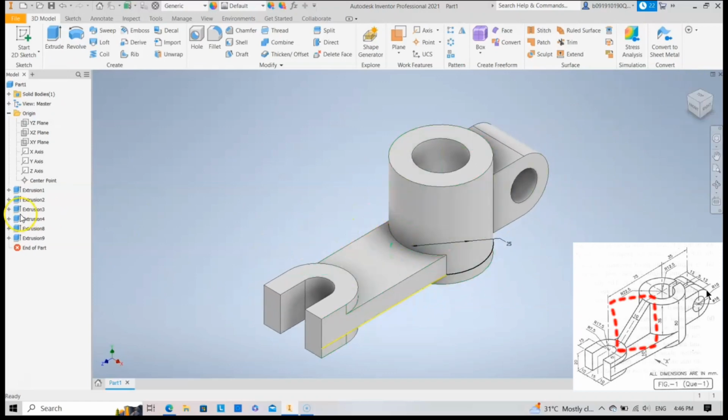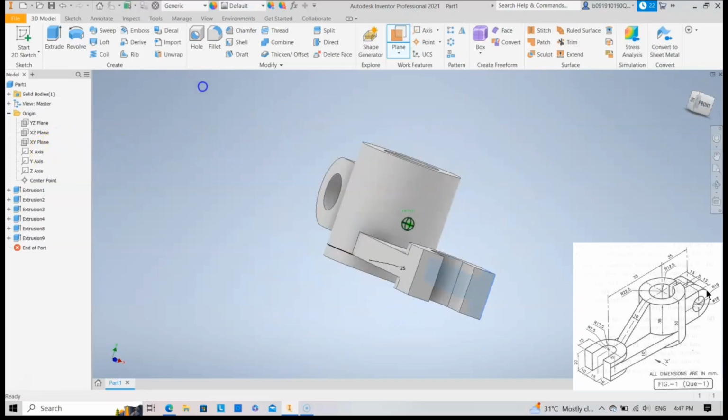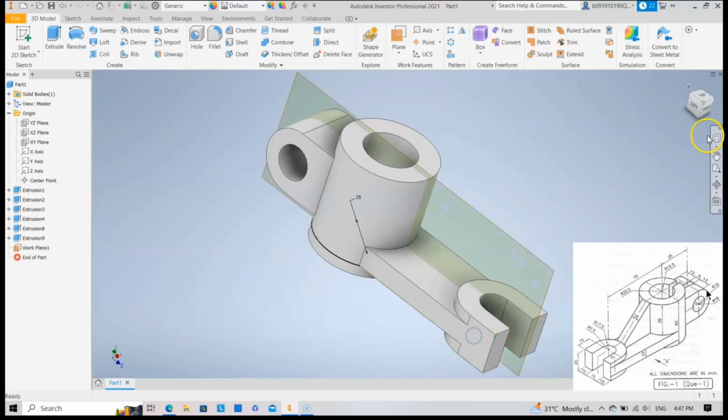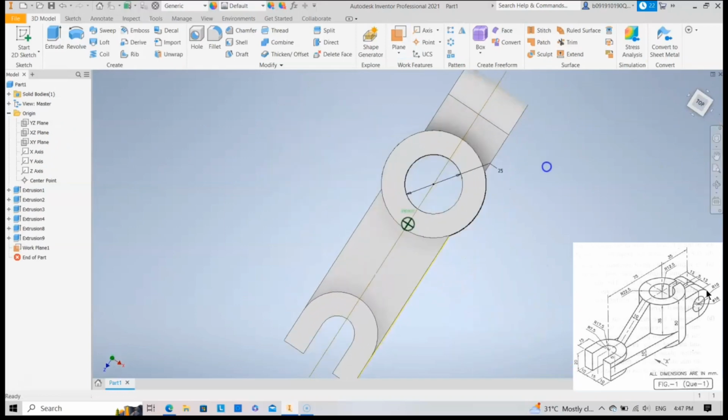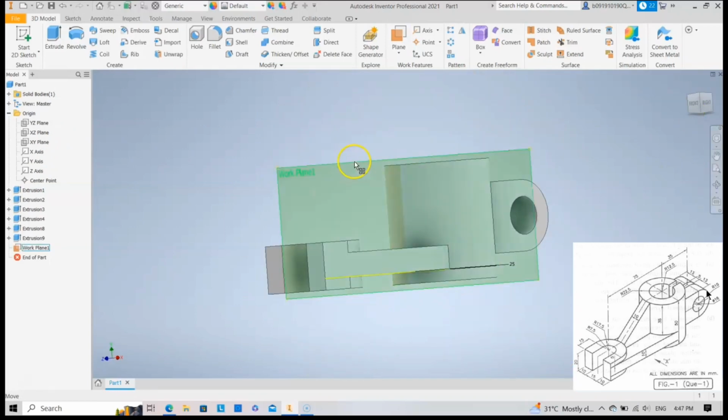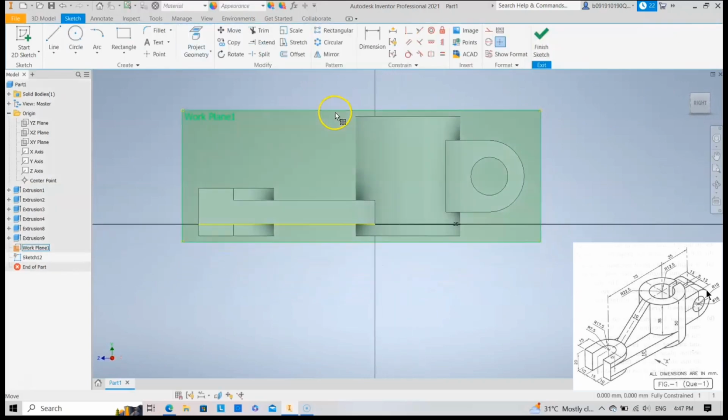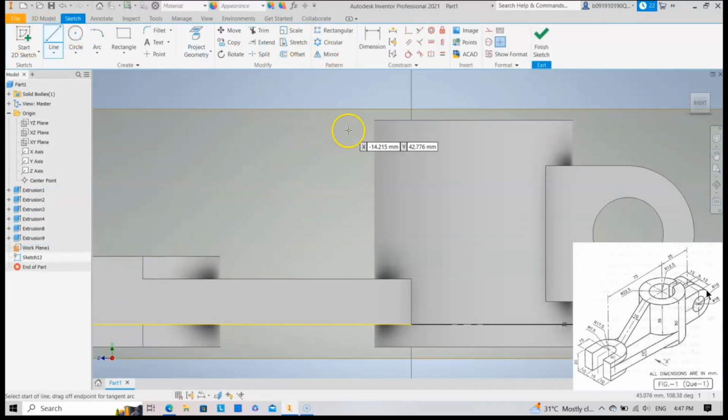As for the triangle part beside the circle, use Work Plane tool, click the right and left side of the face to get the copy of YZ plane to draw on it. Draw a single line and use coincident constraint to stick it on the line of the upper side of the circle and on the arc of the U-shaped surface. Drag the point of the line to the edge of both arcs and the line will be fully constrained.